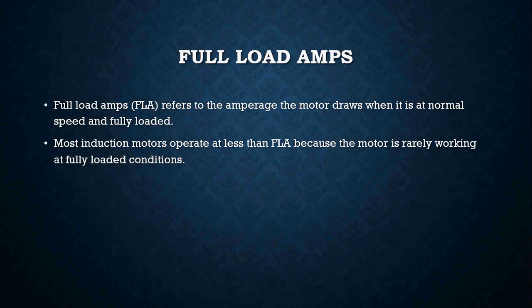Another term that we have to deal with is what we call full load amps, or FLA. Okay, full load amps refers to the amperage the motor draws when it is at normal speed, fully loaded and working at its 100% peak. Okay, most induction motors operate at less than full load amps because the motor is rarely working at full load conditions. So when you're looking at a nameplate on a motor, you may see an LRA rating and an FLA rating.